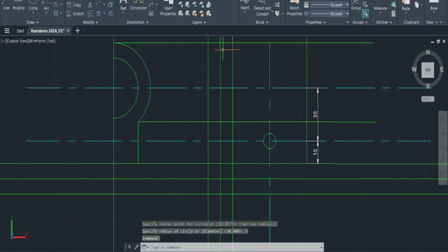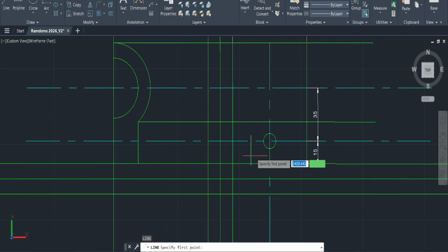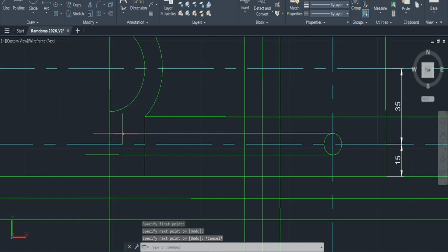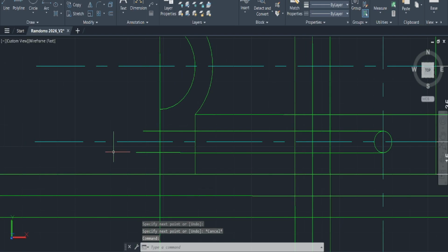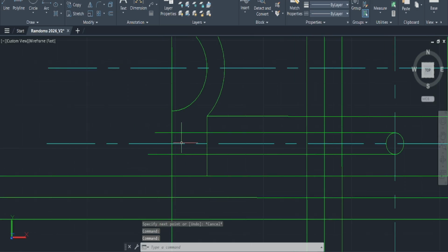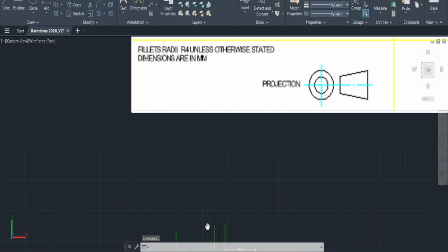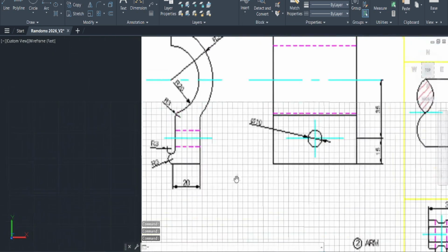and there we have our inner circle. I'm gonna use the construction lines to project the lines across on this other side of the drawing. So we're just pulling that across, so I know now that the hole itself is actually going to be hidden lines coming across here. Awesome. The next thing for us to actually draw will be the bumps and the curves that we highlighted earlier on.